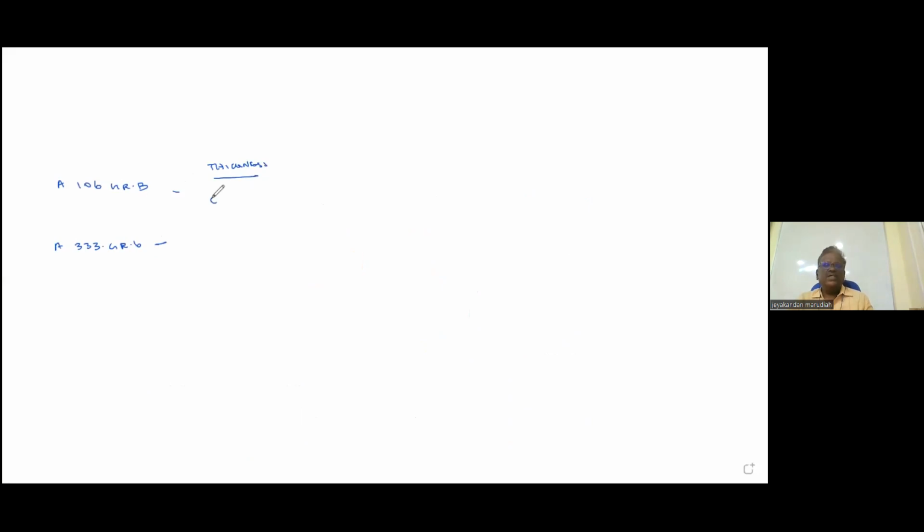I will take a common thickness of 0.75 inch. Now what we are going to find out is MDMT. What is MDMT? Minimum design metal temperature, MDMT without impact test.